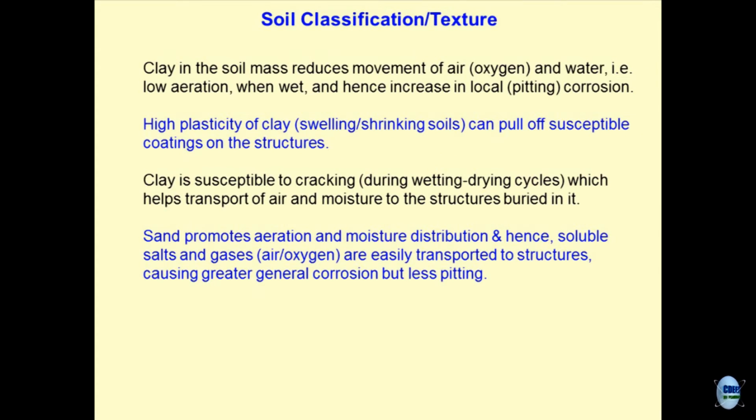Most of the time when we do piling, we use different types of epoxies. You must have come across this, particularly with what type of piles? Driven piles or precast driven piles. So, what normally is done is that after the piles have been cast, there is a coating given on the piles to enhance their life, particularly in environments which are extremely aggressive, offshore environment particularly.